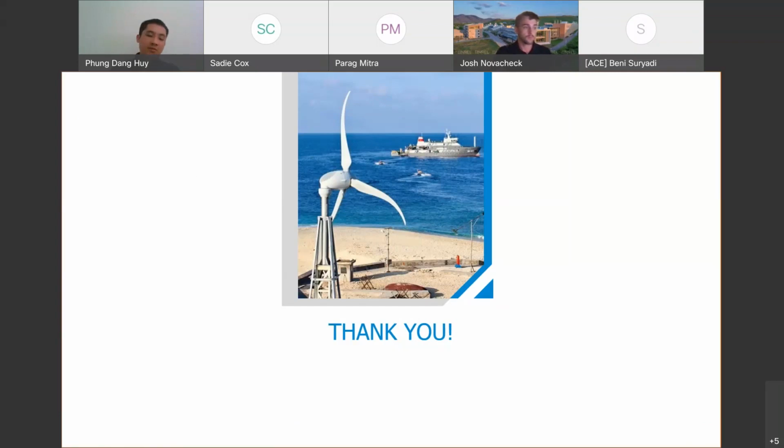The RoCoF is currently not yet written in the standard. The RoCoF of 0.05 that we have used as the minimum criteria is based on our normal RoCoF, which is about 0.04. We think that if it goes above that, then it should be a problem.